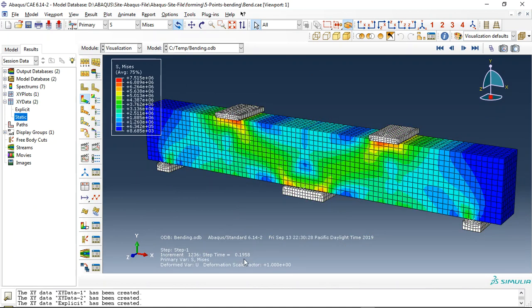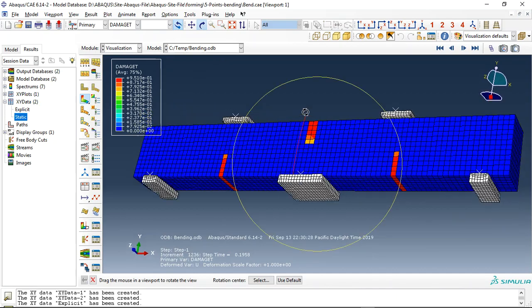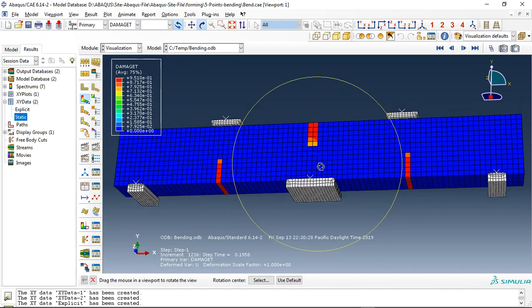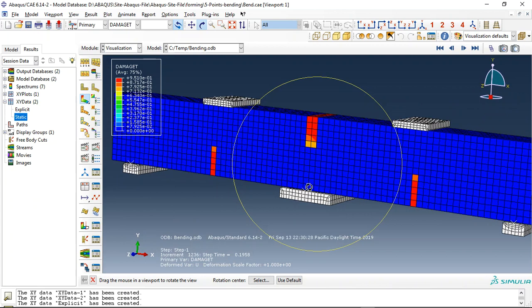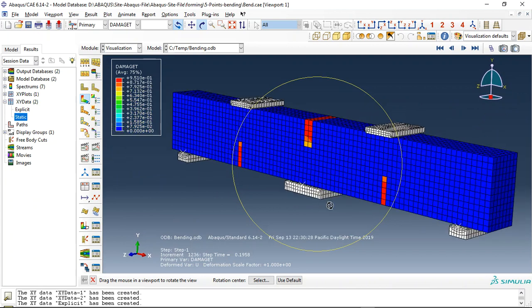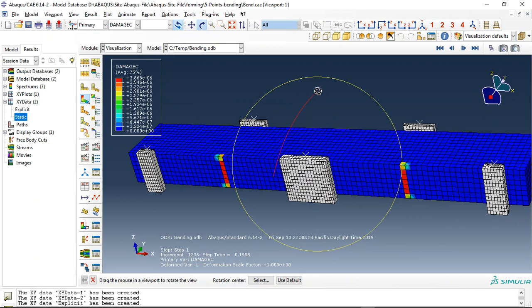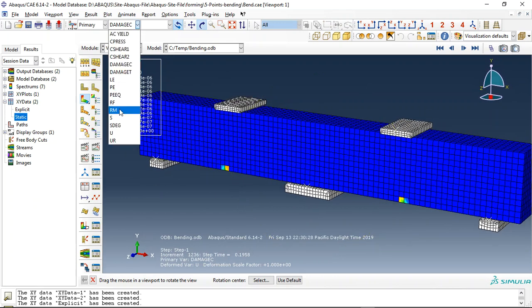You can see that, and the time for that is 0.19 second. And at this point, the non-convergence happened because of the tensile damage. The tensile damage decreases the target time, minimum time increment to microsecond, and it needs time, for instance 2 days, to be complete, or the compressive damage. Here you can see that.